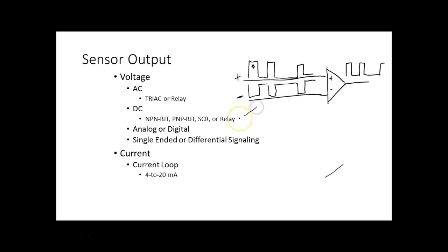But we don't use 0 volts as a reference anymore, right? You understand that? Exactly what you said. We would have a positive voltage and we would have a negative voltage all the time. But every time we're sending something, we'd always have a difference in potential. And what the differential amplifier does is only let what's moving in different directions pass through.